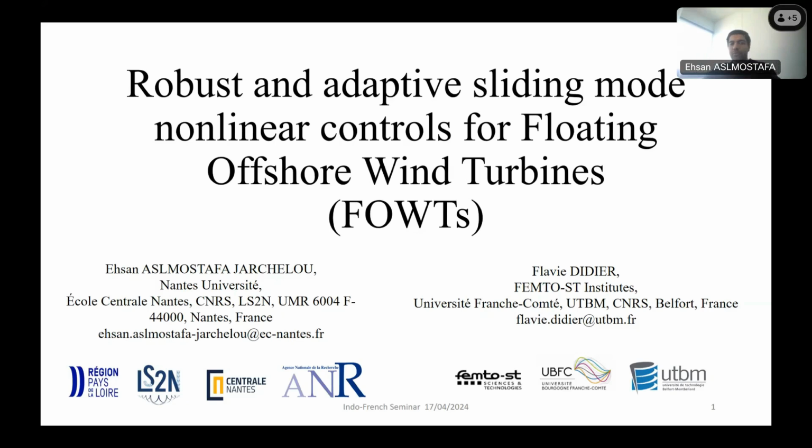Different platforms for floating offshore wind turbines are presented. Here you can see 4 of them: the spar-buoy platform, the semi-submersible, the tension leg platform, and the barge platform. The advantage of using a floating wind turbine is having a strong wind off the coast with very little disturbance to the wind profile. This means that we can have a higher power range than today's wind turbines.